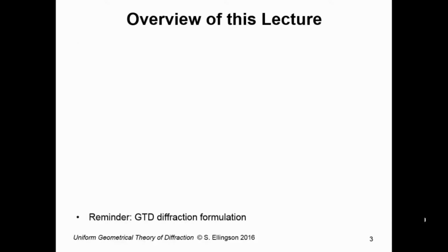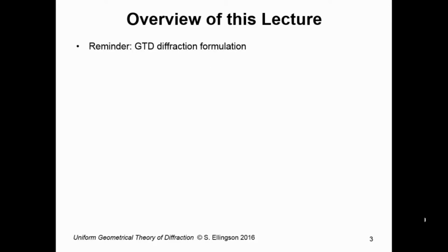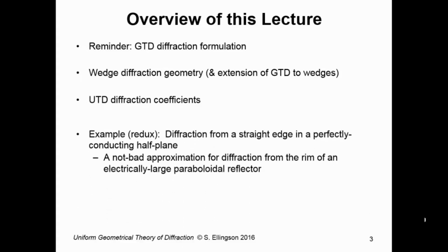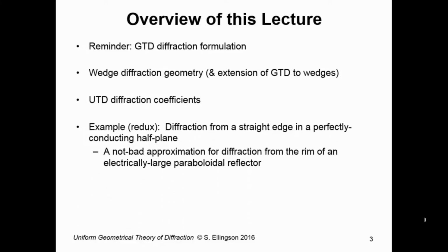Okay, an overview of this lecture. First, I'll remind you about the GTD diffraction formulation. We'll introduce wedge diffraction geometry. So we're extending the problem to that of wedges, not just simple edges. And then we'll extend GTD to wedges. I'll introduce the UTD diffraction coefficients, and then we'll return to this example that we previously addressed, that is, diffraction from a straight edge in a perfectly conducting half plane.